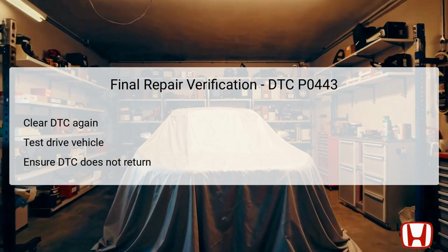Once repairs have been made for DTC P0443, it is essential to proceed with final repair verification to confirm that the issue has been rectified. Start by clearing the DTC one final time using the Honda Diagnostic System, HDS, to ensure that the system is reset. Follow this by taking the vehicle on a test drive under various driving conditions to appropriately replicate previous scenarios that may have triggered the error code.